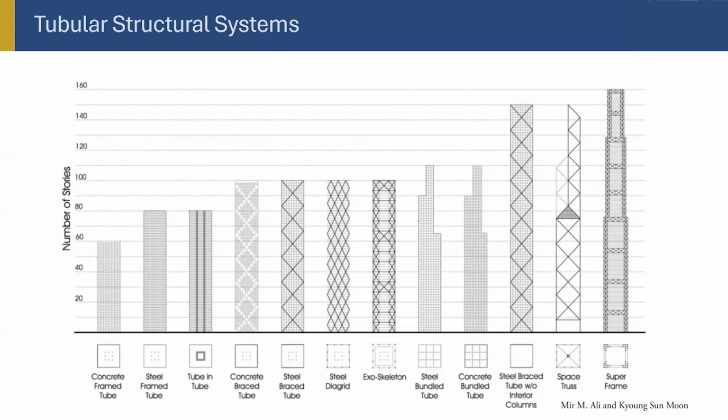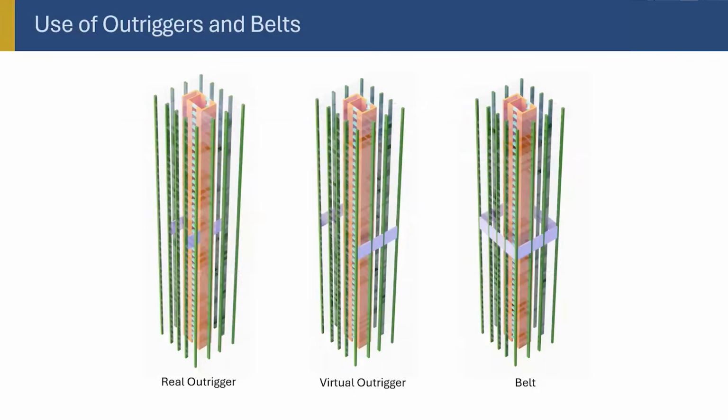So this is a very different concept, that instead of considering every column to be load bearing, you just consider 4 columns to be load bearing, make them very big. Instead of every beam to carry the load, you just take those. So just convert the building from this one to that one, just changing the size of the beam, height of the beam. It's a very simple concept, but it works very well. And this can go very far. So that's the idea. So these are some basic variations of the 2 systems.